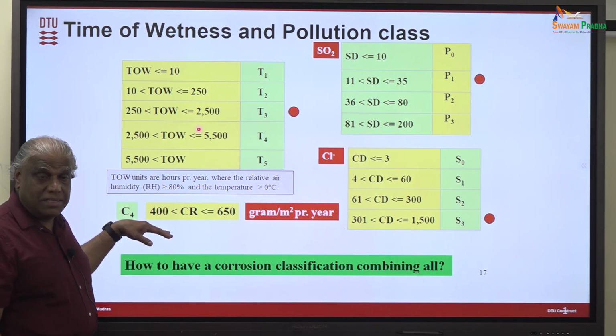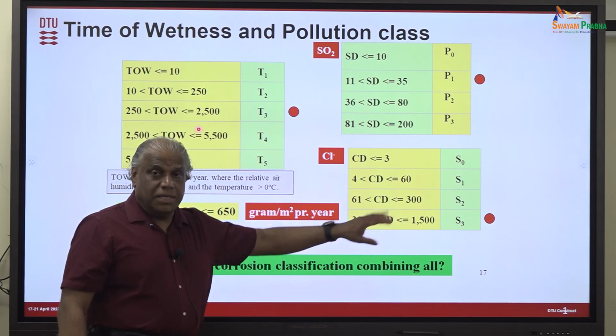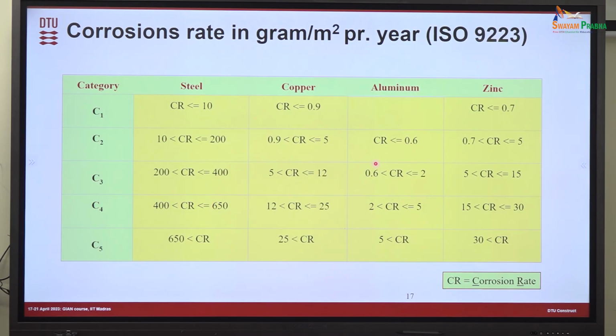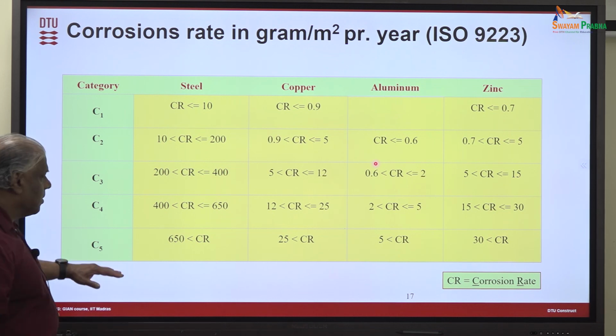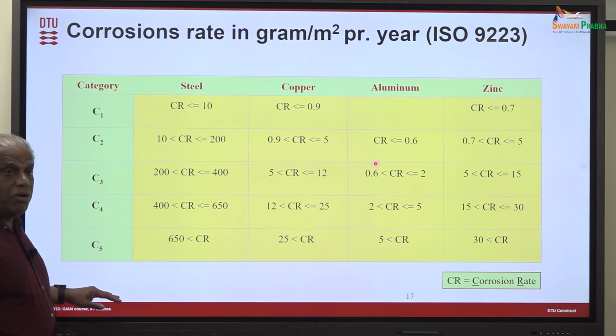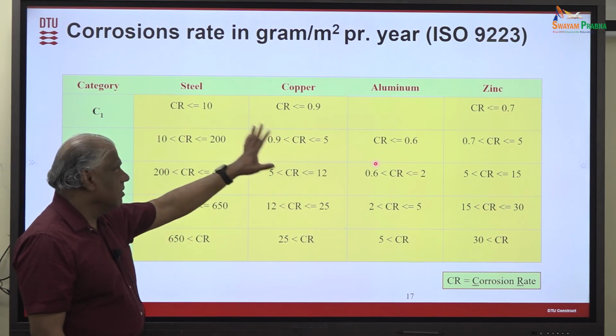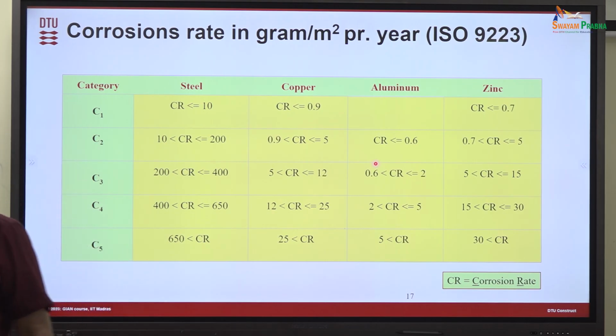There is also a corrosion class division between the places, which is determined along with all these by using coupons at different places, and that shows as a corrosion class, which is very, very important together with all these. Then we divide it into C1 to C5, and people also sometimes talk about the CH class, which is totally offshore. This is the corrosion rate, and they determine the corrosion rate for main structural materials, which is a very good indication for predicting.